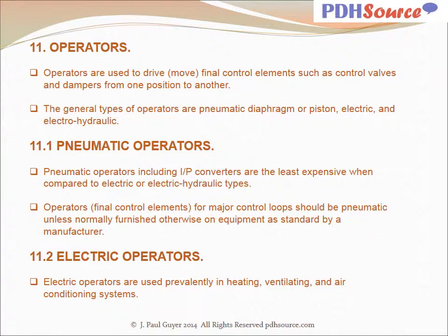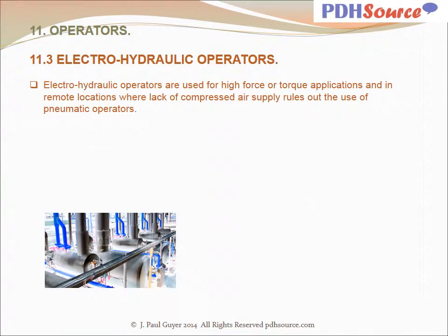Operators, final control elements for major control loops, should be pneumatic unless normally furnished otherwise on equipment as standard by a manufacturer. Electric operators are used prevalently in heating, ventilating, and air conditioning systems. Electro-hydraulic operators are used for high force or torque applications and in remote locations where lack of compressed air supply rules out the use of pneumatic operators.